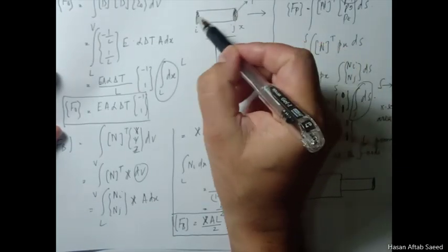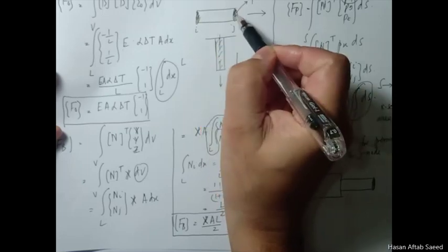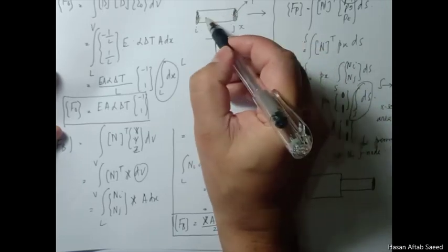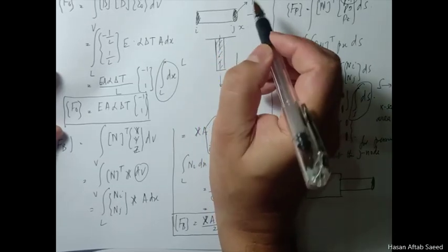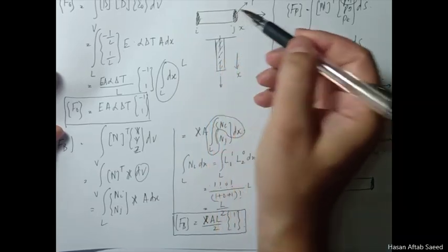It makes sense. If the body force acts on the whole element, then half of it should go here, half of it should go here. Remember that for FEM there is no scope of applying the force anywhere in between. You can only apply the forces on the nodes. Actually they are applied on the whole body, but you apply them on the nodes.